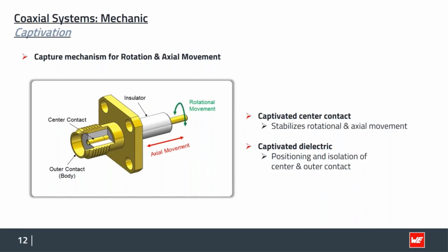Sometimes if you unplug, you feel a little bit of movement in there, where the dielectric material starts to slip, to slide. This is of course something we want to avoid, because if this slides, we have an air gap somewhere. So we again have the problem of changing materials and getting reflection.